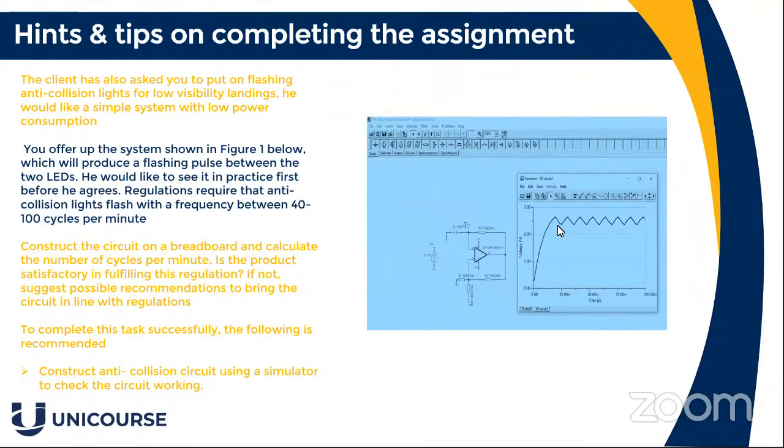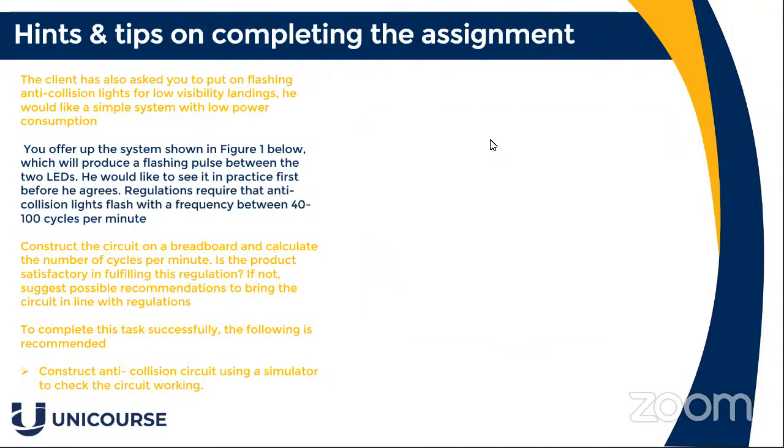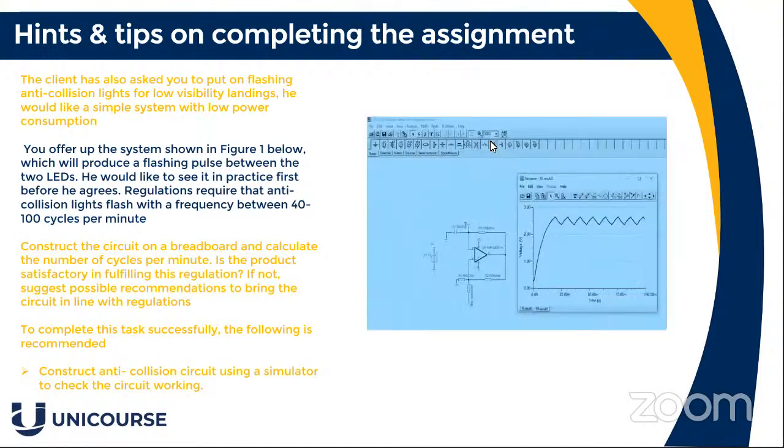What is important is that by using one of the simulators, you should hopefully quickly see what the frequency is. But please note that when you build it on breadboard, this is giving you what is probably a textbook reading. In other words, the resistors and the capacitor have no tolerance. It's just 30 microfarad or 10K, whereas on your actual physical one, you may have tolerances of up to plus or minus 10%, and you may have some resistance in the wires. So as long as you get a similar result, it shouldn't be too bad.